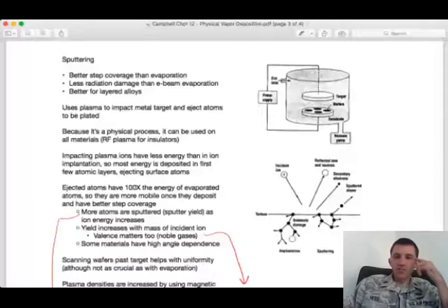First of all, remember up here in this expression for deposition rate, we assumed that we had a constant temperature across the surface and a constant area. Well, if I'm heating up some small region of my charge, it'd be hard to estimate how big is that region that's actually molten? And the temperature is going to be non-uniform, kind of on purpose, right? Because I want the outsides to be cool so that I don't have contamination from my crucible.